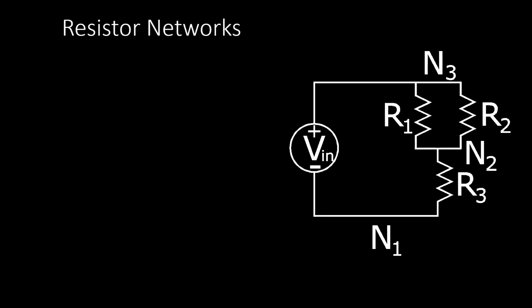All right, so now let's put that into practice. So if we have this circuit where we have a bunch of resistors on this side being supplied by this power supply, and say we wanted to figure out how much current the power supply needed to provide, we could simplify the circuit by creating an equivalent resistor that represents the whole circuit.